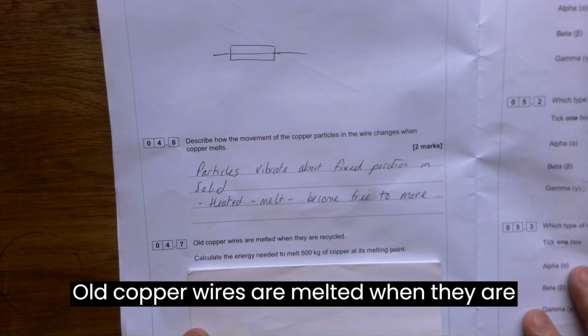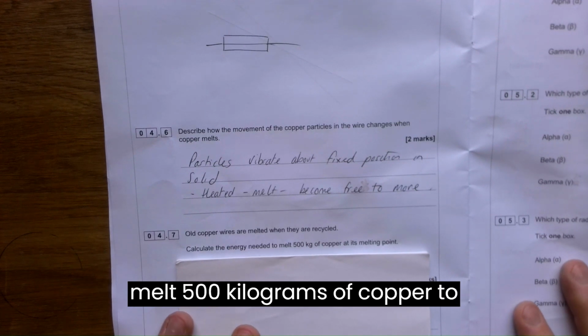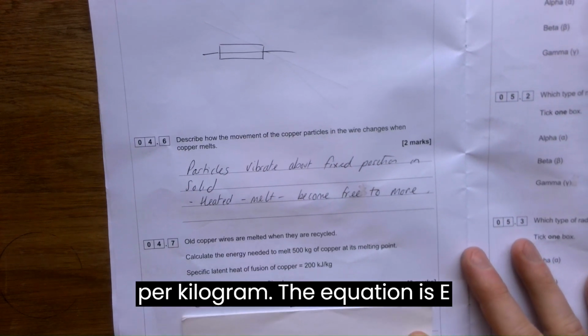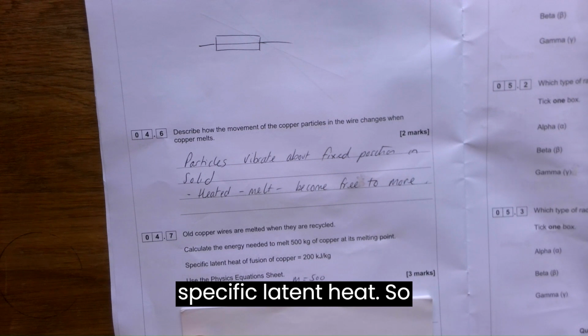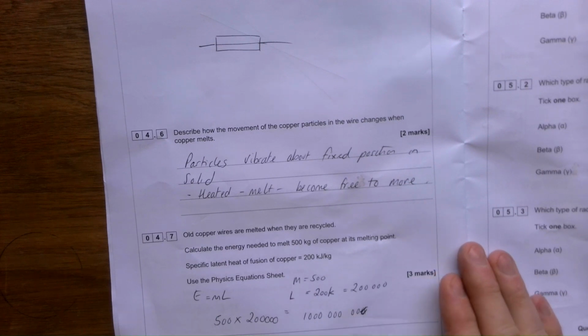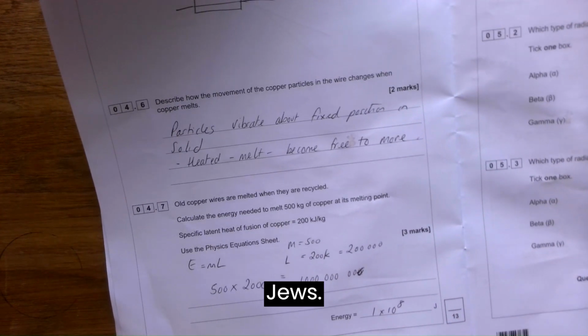Old copper wires are melted when they are recycled. Calculate the energy needed to melt 500 kilograms of copper at its melting point. The specific latent heat of fusion of copper is 200 kilojoules per kilogram. The equation is E equals ml. Energy is mass times specific latent heat. So 500 multiplied by 200,000 is 1 times 10 to the 8 joules.